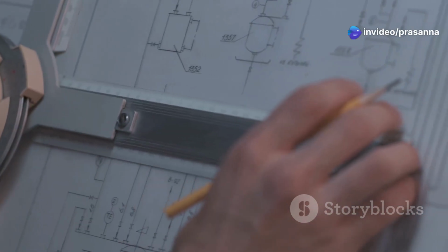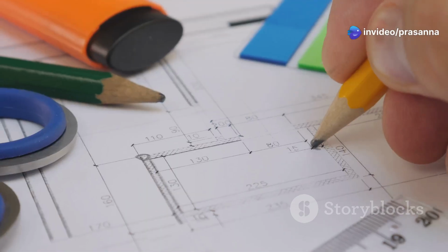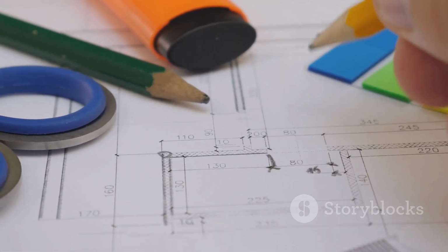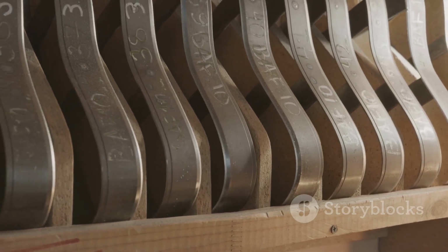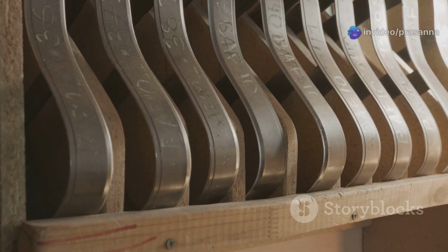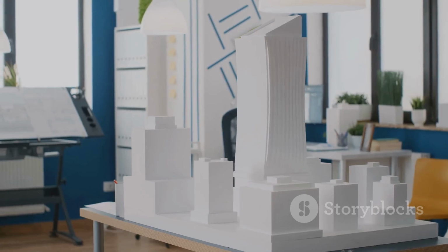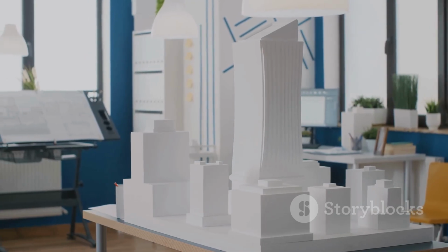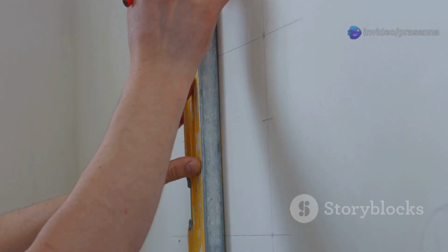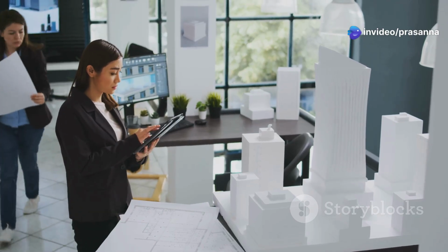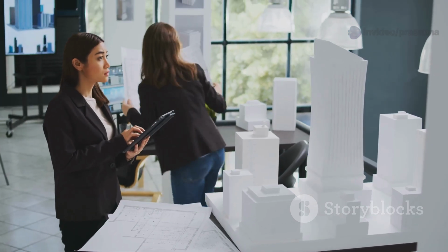It is important to think about wall thickness too. If your 2-dimensional plan only shows a single line for walls, you will need to create thickness. You can use the Offset tool on your floor plan before pulling the walls up. This creates 2 parallel lines representing the inner and outer faces of the wall. Then you can pull up the area between these lines. Alternatively, you can pull up a single surface wall first, then use push-pull again on one face of the wall to give it the desired thickness. This ensures your model accurately represents real building construction.